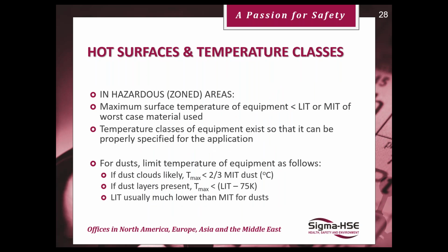We can do it when we look at it from the energy input being temperature, we can look at hot surfaces and we can build equipment that will only generate sufficient heat. So you can get electrical motors, some of which will run very hot and others will run at a much lower temperature. This is known as the temperature class.